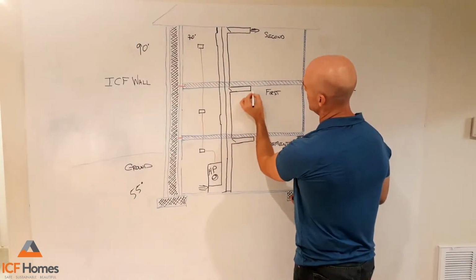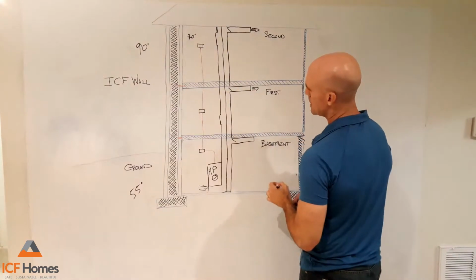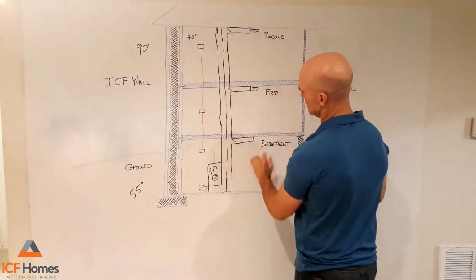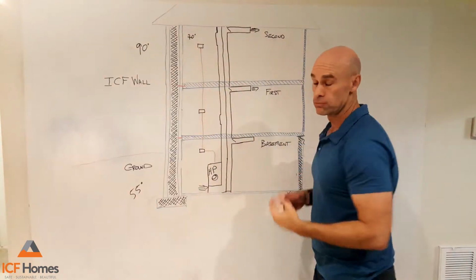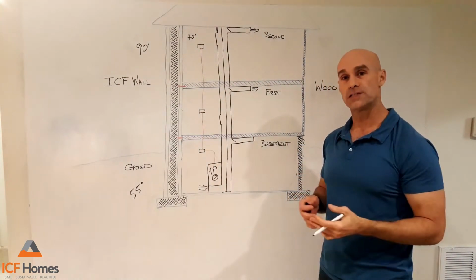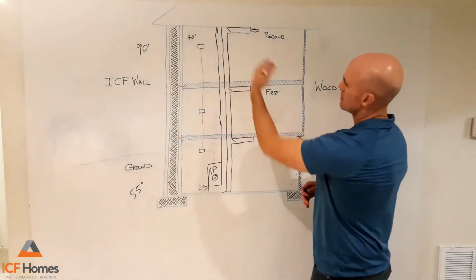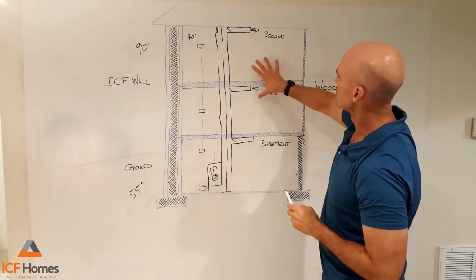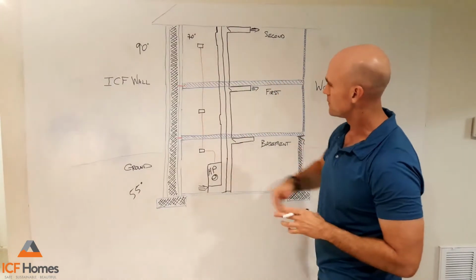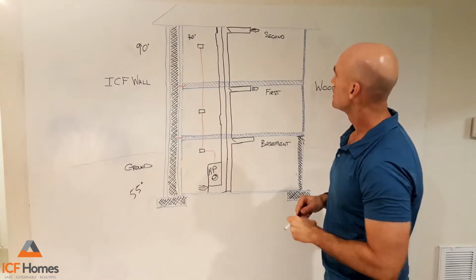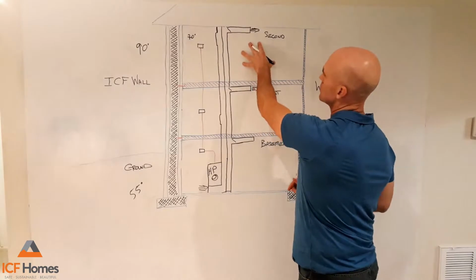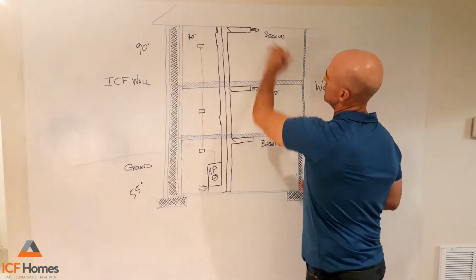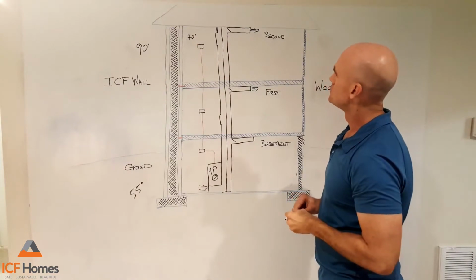This damper opens up and we blow cool air out. The whole goal is to move the air from the basement all the way up to the top of the house and back down, up and down. That's really good convection in a home. Movement of the air around keeps the air very, very fresh and moving around. This is also the only energy this requires, just the fan of the heat pump. If for some reason we need more cooling up top, the heat pump turns on, these dampers close, and it blows out cool air at the top.